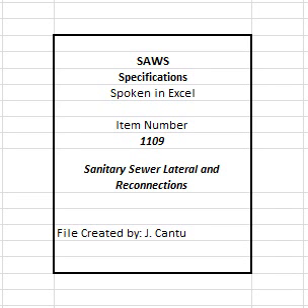E. Complete reconnection of service lines within 24 hours after disconnection due to slip lining, parallel, or replacement of sanitary sewer mains. F. Reconnect services on cured in-place pipe, CIPP, without excavation, utilizing a remote-controlled cutting device, monitored by a video TV camera. CIPP will be completed per Item 901, Rehabilitation of Sanitary Sewer by Cured In-Place Pipe, Hot Water.